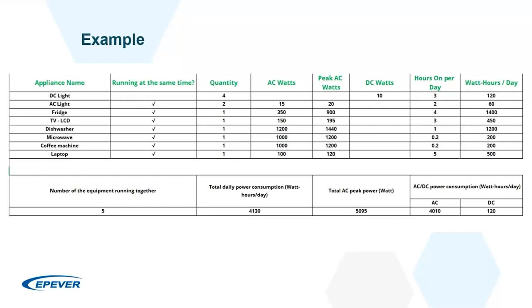So, for a brief time after being switched on, maybe only for a few milliseconds, electrical appliances often draw a significantly higher current than their normal operation. It could be up to 30 times higher, for example, for motor loads. And this inrush current is different for different devices. For LEDs it is different, for motors it is different, for a PC it is different.